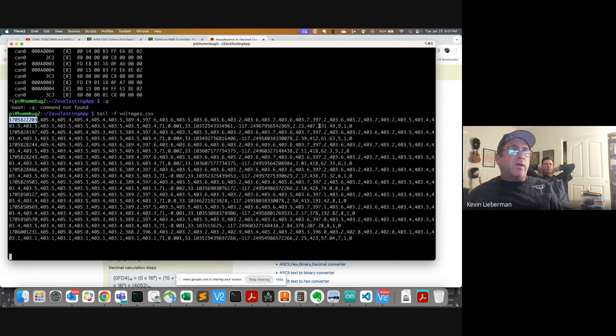So for example, I'm trying to find where my weakest cell is. It doesn't always show itself while you're sitting in the garage or while you're charging. Sometimes it's when you have your foot all the way to the floor. You want to see which battery module, which battery cell is dipping down the lowest, and that's probably your next one that's going to go on you, or that's probably your weakest link in the chain.